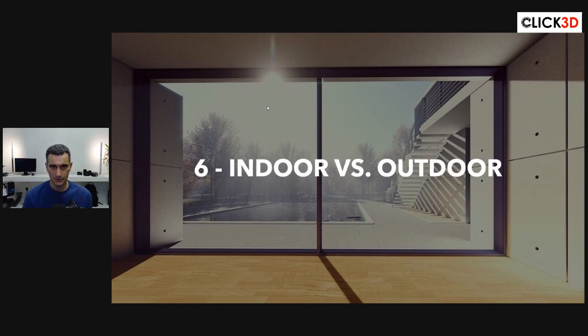Indoor versus outdoor documentation. So what's the difference between scanning indoors versus scanning outdoors, or doing photogrammetry indoors versus doing photogrammetry outdoors? Well, if we're indoors, photogrammetry has a little bit of a disadvantage. Okay, so typically when we take the camera and we want to photograph an object, we want to move around the object. Photogrammetry does great when it can get around the object. So if you're outside and there's a house and you can take photos by walking around the house or flying a drone and doing almost like a circle or a ring around the object, photogrammetry works great.